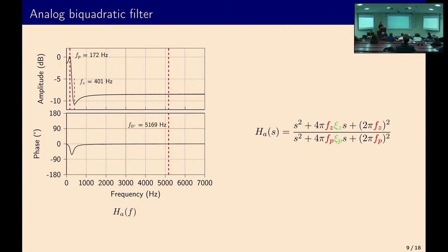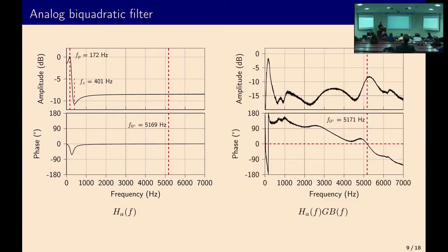If we introduce this control filter inside the feedback loop, we now obtain this result. You see that the unstable frequency is more or less the same as before, 2 Hertz higher actually. But now the amplitude at this unstable frequency is not the maximum anymore. We have an increase, a peak in the low frequency, which actually comes from the control filter we just introduced. So this gain margin we have is actually the attenuation we'll get when increasing the gain. The low frequency will be amplified, but before we get instability, we will have attenuation happening. Okay, so this is great.